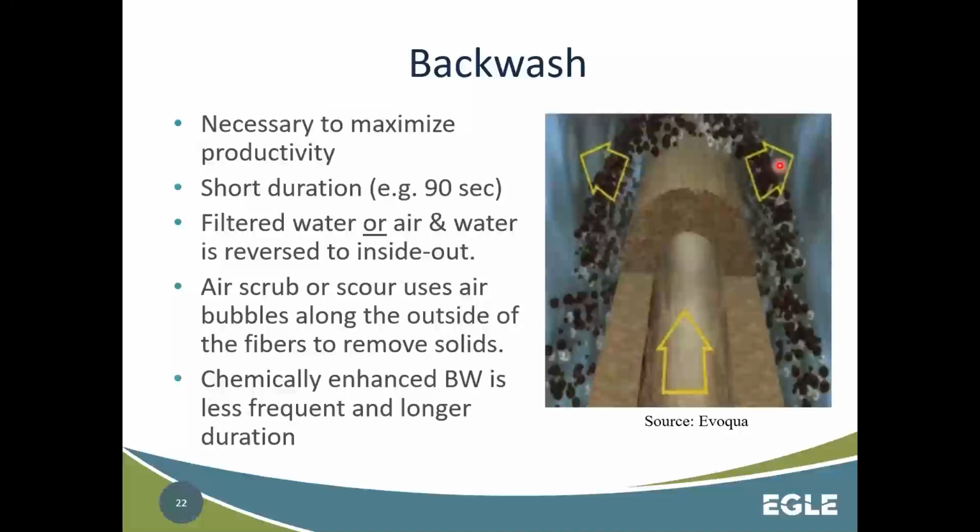And then a lot of times they'll also introduce compressed air on the outside of the fiber. And so you get air bubbles that kind of agitate. And so between the reversal of the water plus the agitation with the air, it does a pretty good job of clearing those particulates off, and then it just goes off to waste.